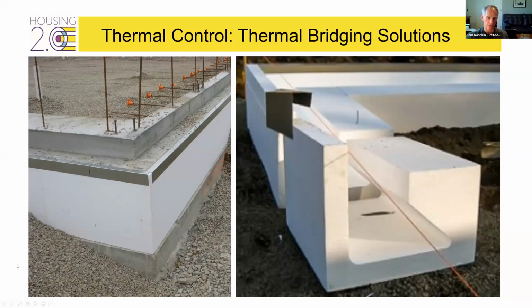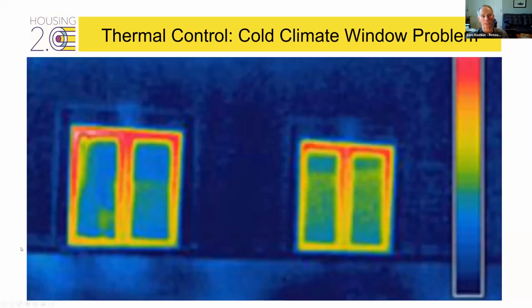Don't forget, the ground temperature year-round is about 50 degrees in most climates, 55 in the more mild climates. So I'm always amazed to see how much slab and foundation insulation is used, particularly in passive homes. I don't know how it could be cost effective beyond a couple of inches below the slab, but these are great solutions that we can look for.